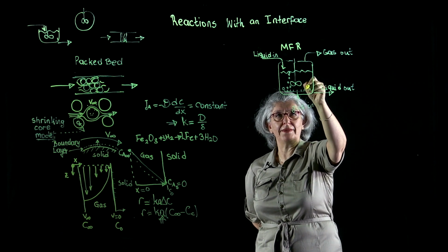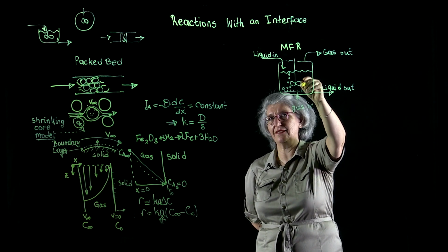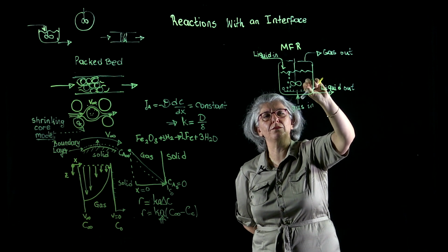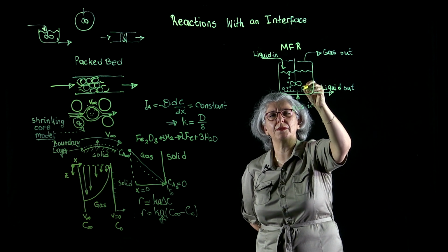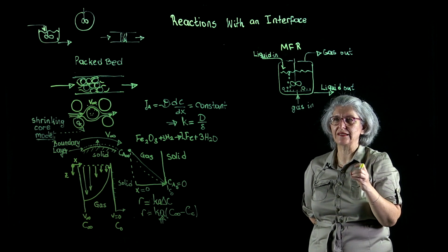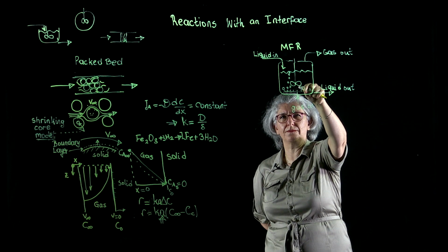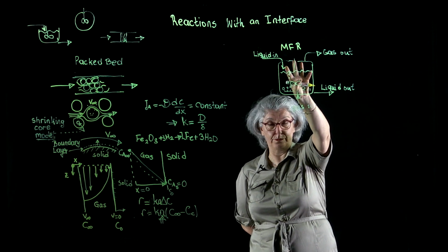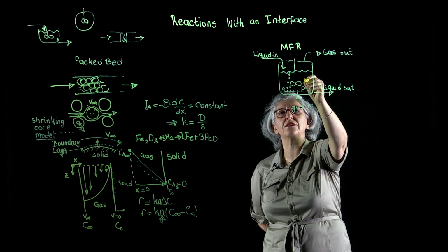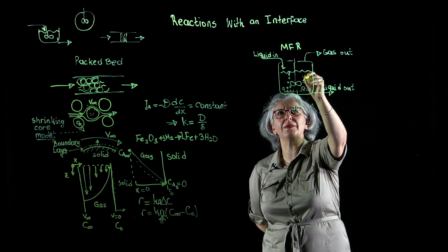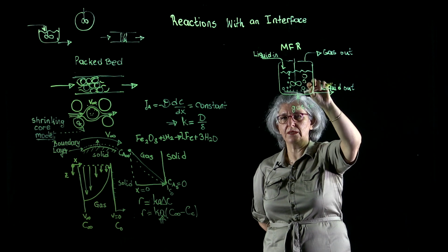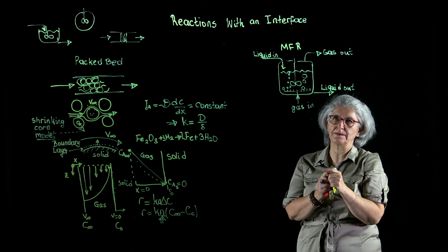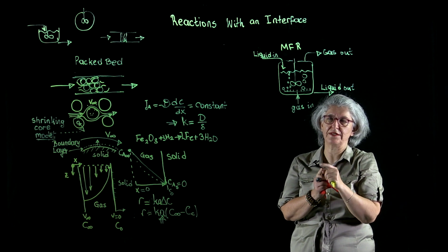Now, because of the hydrostatic head, the bubbles at the bottom will have a size due to the hydrostatic pressure. If nothing happens, as they move up through the buoyant forces, they should start getting bigger and bigger. As they move up, their size should increase because the hydrostatic pressure decreases as we move up.